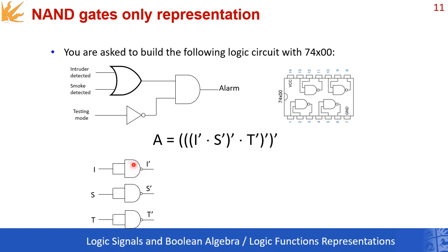Remember that we only have NAND gates, which is why we use the NAND gate here by passing the same variable twice in both inputs. So every variable which is passed twice to a NAND gate works like a NOT gate and inverts the input. So far we got everything that we need.